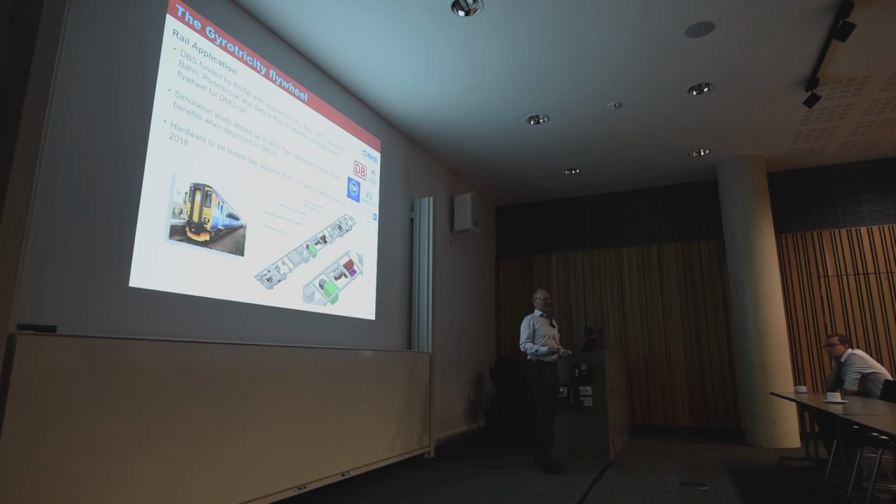How can we significantly reduce fuel consumption? We showed we could reduce fuel consumption in simulations, proper full simulations, by up to 40% for a DMU. And we could do this mainly, it's not just the flywheel, actually, energy recovery. We don't need a particularly big flywheel. It's the fact you turn the diesel engine off. You can turn the monster off when you don't want it.